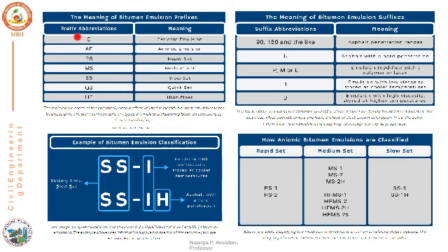When we use any prefixes C, AE, RS, MS, SS, QS, HF, etc., C stands for cationic emulsion, AE for anionic emulsion, RS for rapid set, MS for medium set, SS slow set, QS quick set, HF is the high float bituminous emulsion.